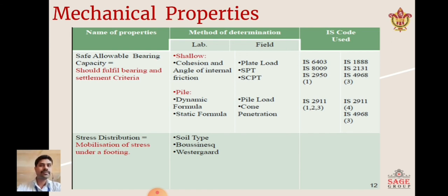These are the laboratory tests. If we want the field tests, then for shallow foundations, plate load, SPT and SCPT methods are used for determining the safe allowable bearing capacity. And if the foundation is pile, then the pile load test and cone penetration test are carried out for finding the safe allowable bearing capacity of the soil.